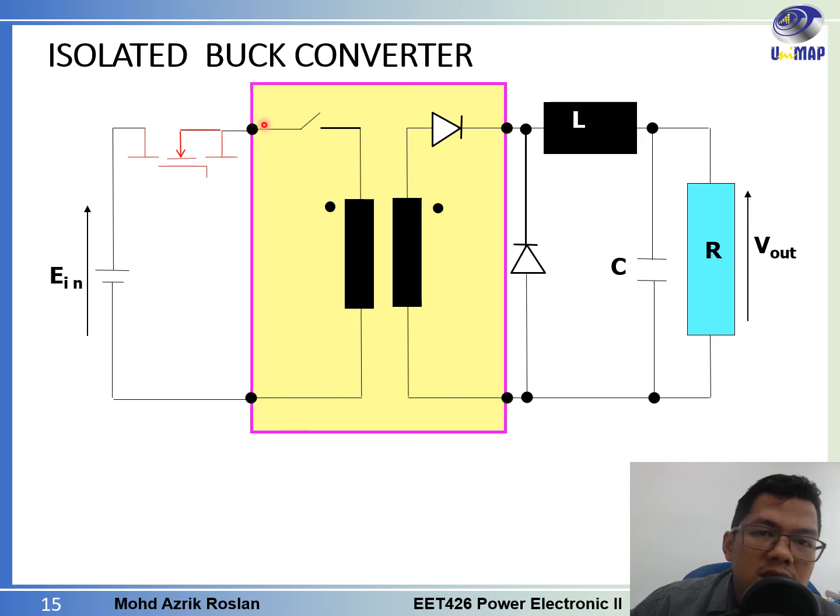If we just put a constant DC supply here, there will be no effect and the transformer will not work, as the transformer works on the principle of induction due to the change of the voltage and current at this side. So if you have direct DC at this point, there will be no fluctuating current, and power will not be induced at the secondary side.